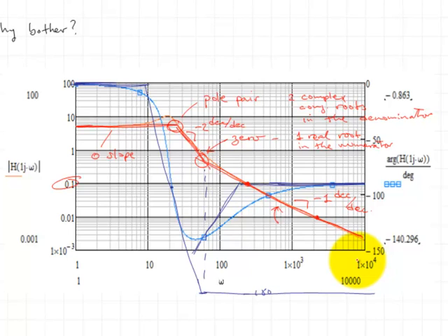And finally, after we've connected all the straight lines together, we recognize that, well, whenever you do have a breakpoint, such as this 0 here, or the complex conjugate pole there, the actual magnitude curve doesn't follow those asymptotic lines exactly. It deviates some around those breakpoints, and then we'll develop a few techniques on determining how we do that and how we estimate that deviation.